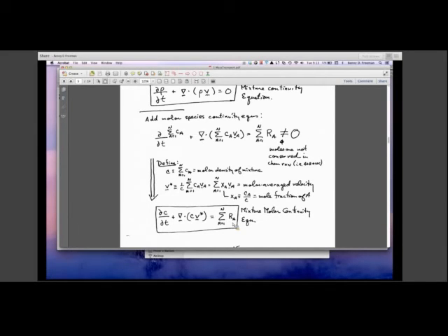And so this molar average velocity is the velocity of each component weighted by its mole fraction. And so we can develop the analog to this expression down here on a molar basis. And it looks very similar, except you have C's instead of rho's. You have a different average velocity, a molar average velocity versus a mass average velocity weighted by mass fraction. And you have this reaction term, which did not appear in the conservation of mass equation.